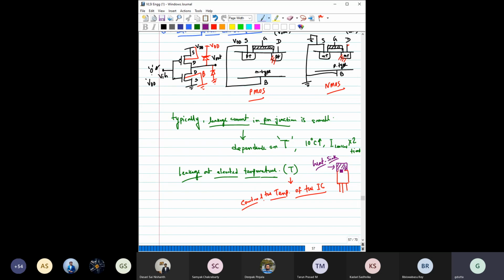One of the important techniques is to use a heat sink. Here you connect a big metal piece compared to your IC, so basically you are increasing the area, and that will dissipate the heat in a better way and try to balance the temperature inside the device. In some cases, the addition of the heat sink alone is not enough. You need to cool it externally. Maybe you have seen in some ICs they have an external fan, which is for cooling purposes. In some cases, they flow some liquid inside a microfluidic channel to cool down the total IC temperature.